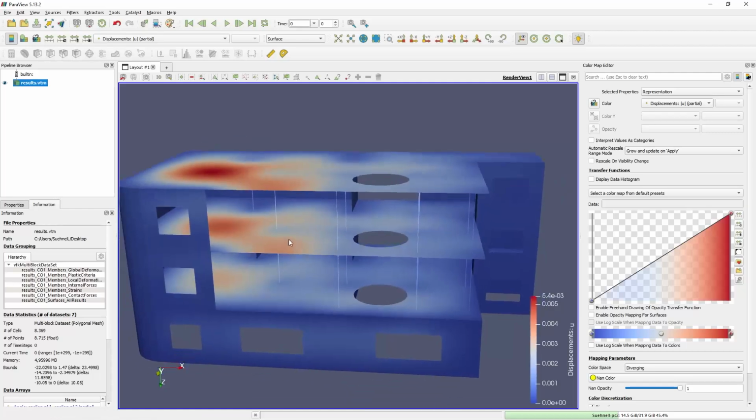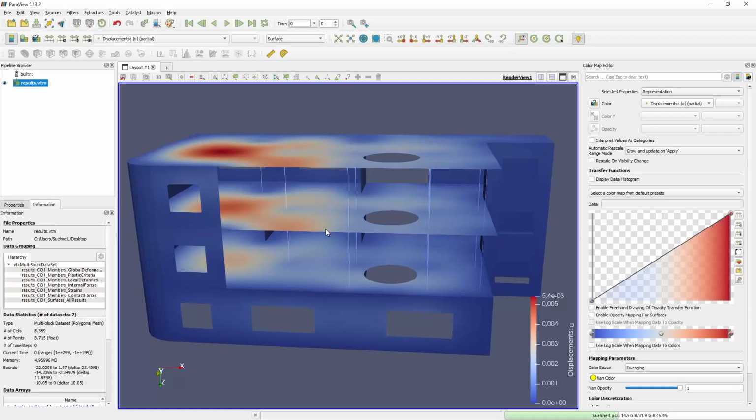So what's the use case of that file format? I could imagine that in case you want to display the RFEM results in your own program for some reason, then you have, in my opinion, two options. You can use our API to read the results that you want to import into your own program, or you're using this VTK file format to export the results into that basically result container, and then read it from that file into your program. That is the use case I can think of.